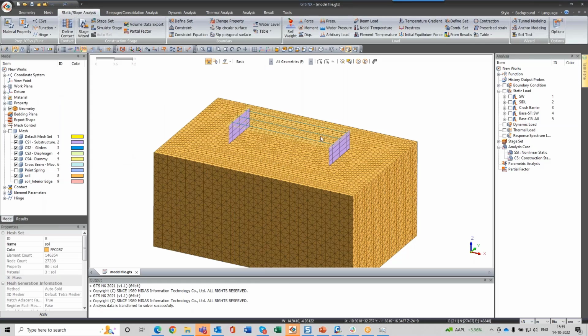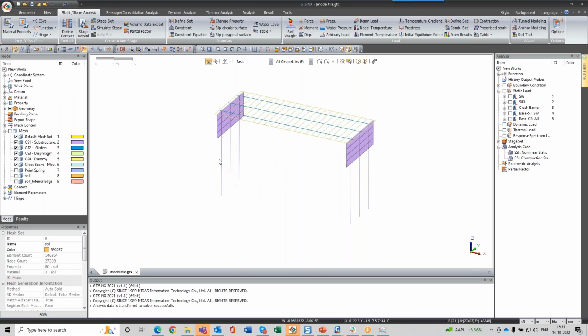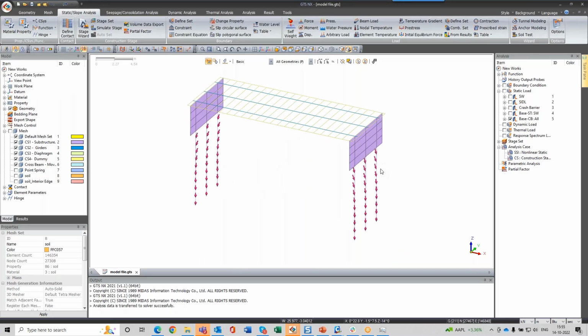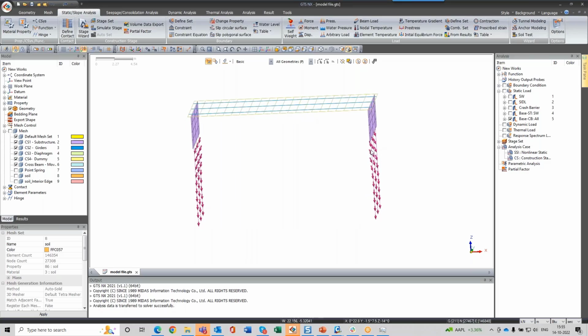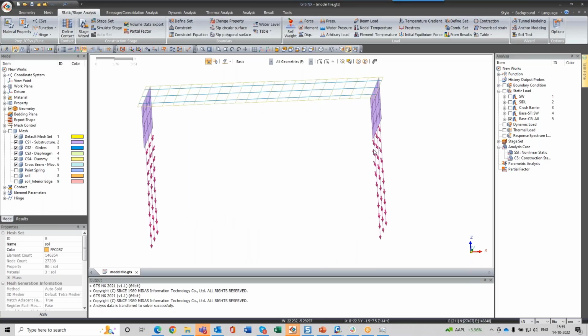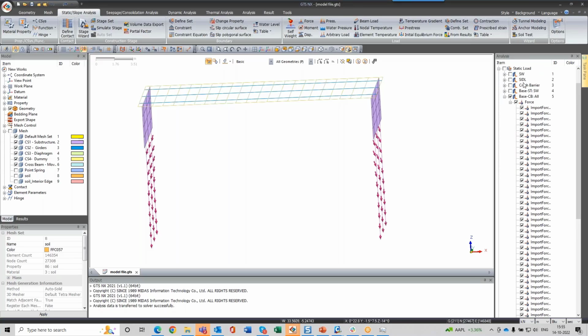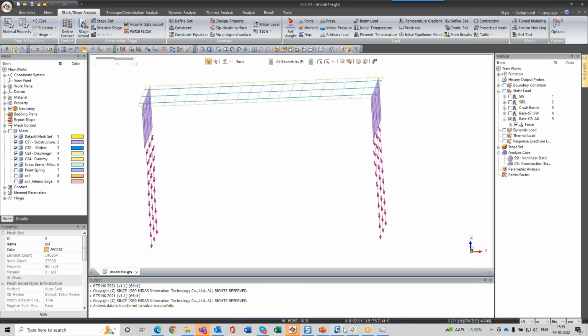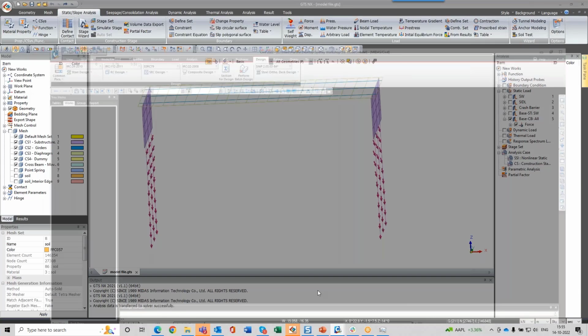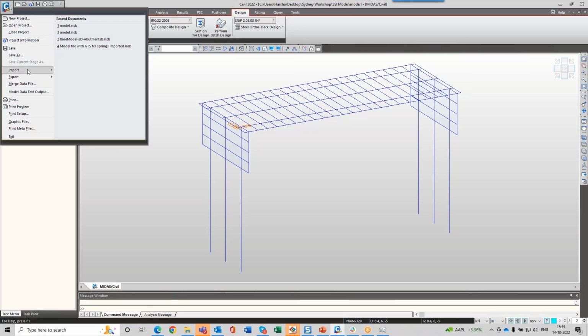And this analysis will be done for some load, right? That load will be either an envelope load given by your structural team or some very critical load combination given by your structural team. So this has to be imported again, right? This can be imported using this particular option. You can go to Civil again, go to export. That means your structural engineer will go to nodal results for GTS NX. So when he does this, all the reactions that you found at different locations come here.